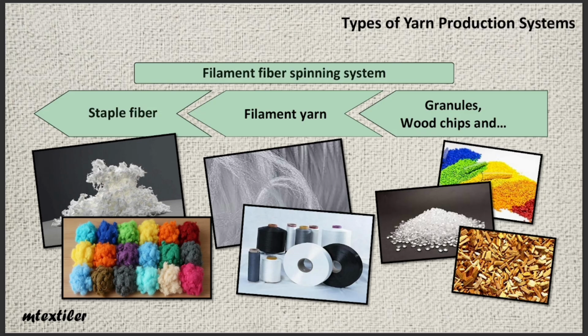It is also important to note that in filament fiber and yarn production systems, we can use master batch or color solution so that colored yarns and fibers are produced right from the start. In this method, the color is incorporated directly into the molecular chains, giving it much greater durability and stability. However, achieving the desired shade in this process requires a high level of experience and skill, and there may be some raw material loss before reaching the exact target shade.